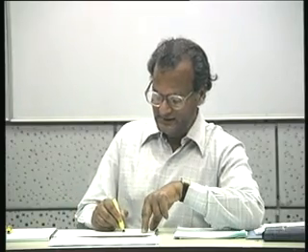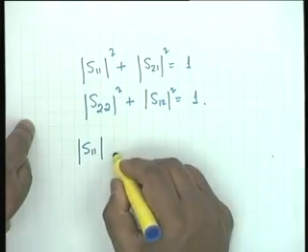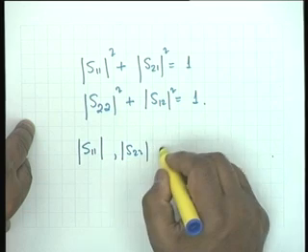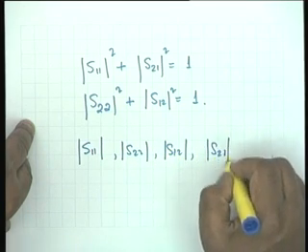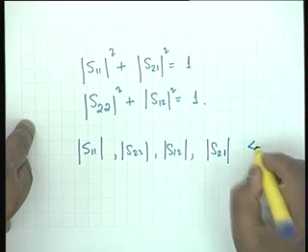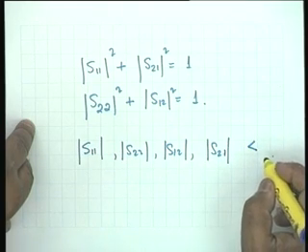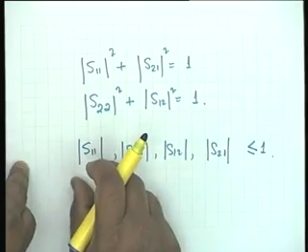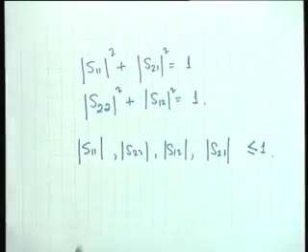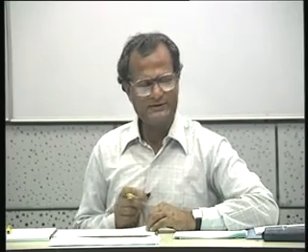That is, S11, S22, S12 and S21, each of them should be less than or equal to unity. One could have one of them equal to 1, then the other one shall be 0. Okay, we'll come to this. This is a very interesting phenomenon. Physically, it's very simple to see.